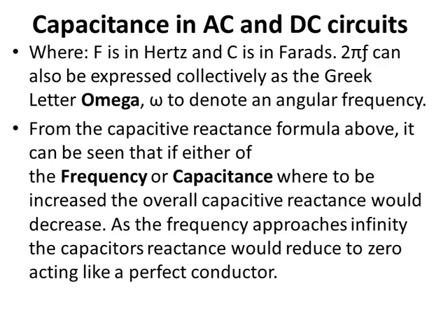Now, capacitance in AC and DC circuits continues here also. I said it's XC, which is our reactance. Capacitive reactance is 1 over 2 pi FC. I told you already that the F there is the frequency, which is in hertz, and the capacitance is in farad, just like we said before. And I also said that your 2 pi F can also be denoted with omega, which is the angular frequency.